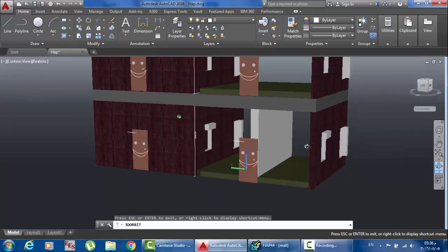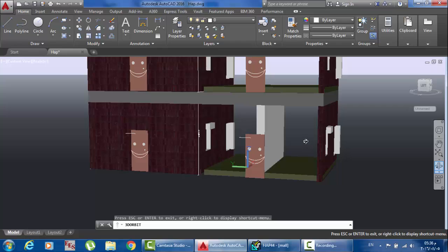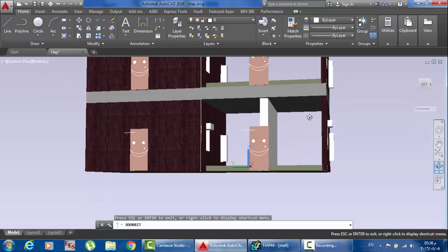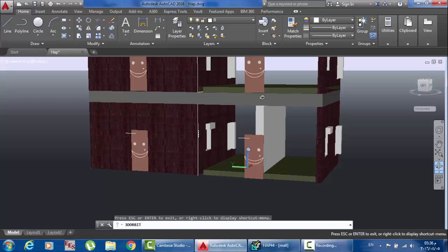If you are not sure that both zones, or every zone, will be at the same temperature at the same time, you may take half of the area of the wall as a partition. Okay, do not take the full area, and take the ceiling area only, and do not take into consideration the floor area.